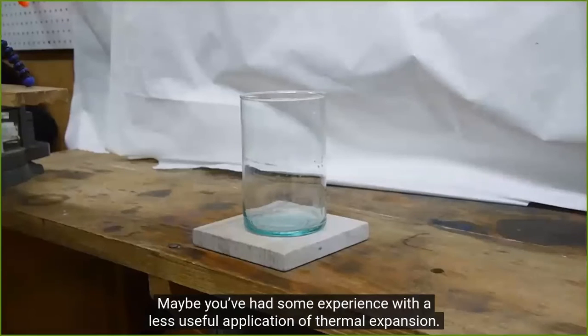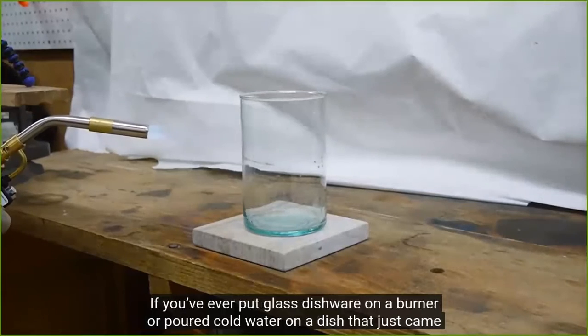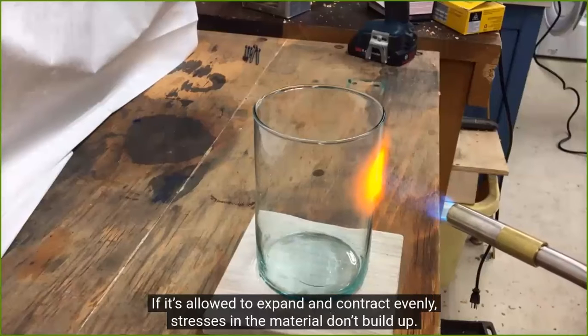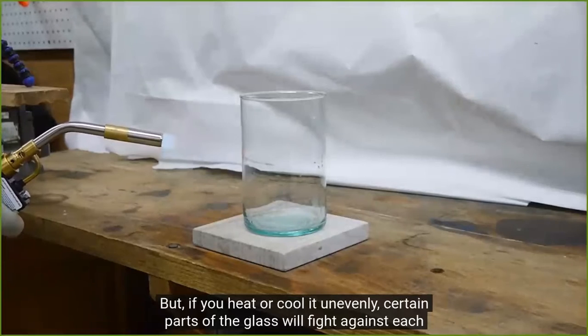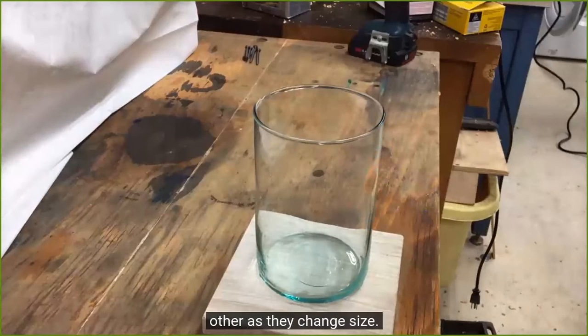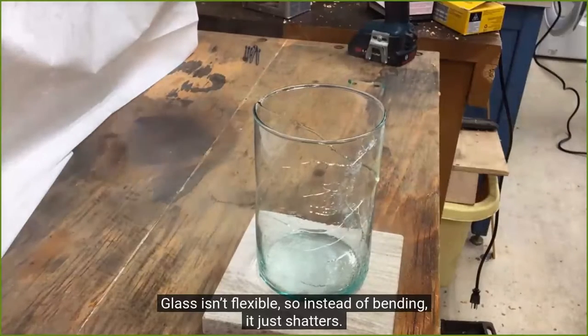Maybe you've had some experience with a less useful application of thermal expansion. If you've ever put glass dishware on a burner or poured cold water on the dish that just came out of the oven, you know it doesn't go so well. If it's allowed to expand and contract evenly, stresses in the material don't build up. But if you heat or cool it unevenly, certain parts of the glass will fight against each other as they change size. Glass isn't flexible, so instead of bending, it just shatters.